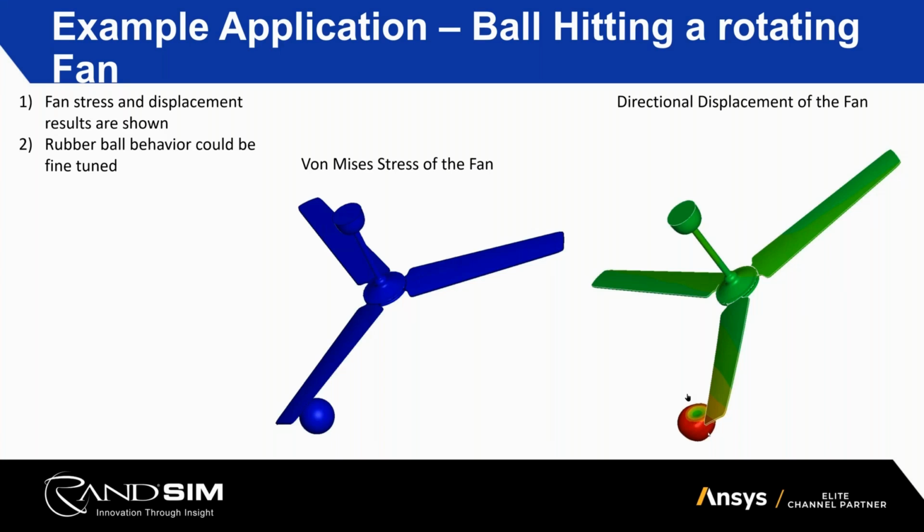Well, implicit problems are usually ones that run longer, and you can really run with as large of a time step as you want. Explicit analyses are limited by, for example, the size of your element, essentially the speed at which sound travels through your material, right? So that limits the time step that you have. But the benefit of an explicit analysis is that you don't have to check for convergence. That's usually a good way to look at it, right? It's essentially a different way to propagate through the state of a system, right?